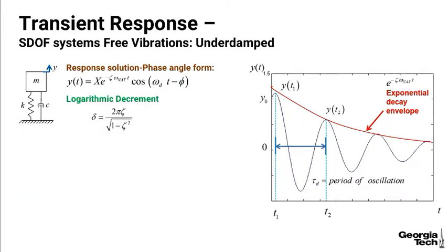All right, so there is our logarithmic decrement. And since I can measure delta, I can physically take a system and I can look at the decaying exponentials of that system. I can measure it in a number of ways. I get a plot like this, and I can plot it out, and then I can find zeta.